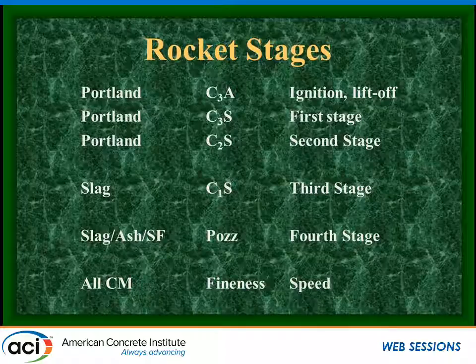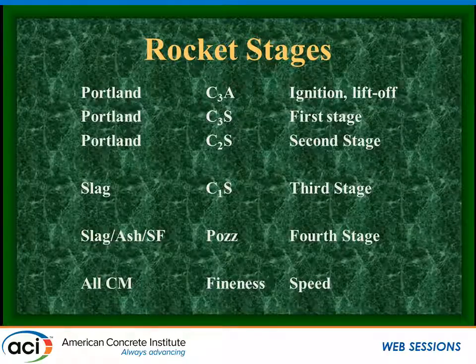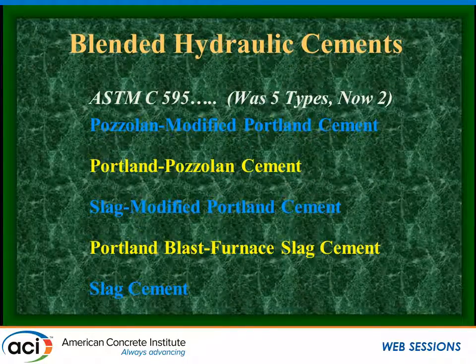And then, regardless of which combinations of these powders we're talking about, the fineness is like our throttle. We can take any of these materials, we make them finer, they're going to go faster. We make them coarser, they're going to go slower. That kind of breaks down just the basics of what we expect to happen and how that sequences out.